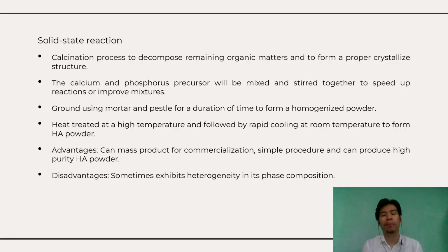In terms of preparation method, this project will be focusing on and using solid state reaction, which is classified as dry method. Solid state reaction usually starts with calcination process of both calcium and phosphorus precursor to decompose remaining organic matter and to form a proper crystallized structure.